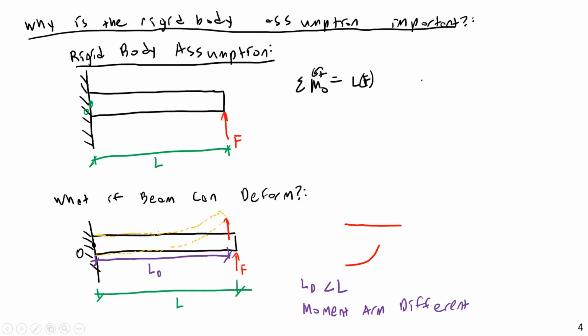So again, if you are designing your beam according to the maximum moment, which we frequently do, and you're applying a force to it, the geometry is actually changing, and the moment arm changes, which means you're changing the maximum moment arm. So the force changes the geometry, but in turn that geometry changes the moment, which affects everything.